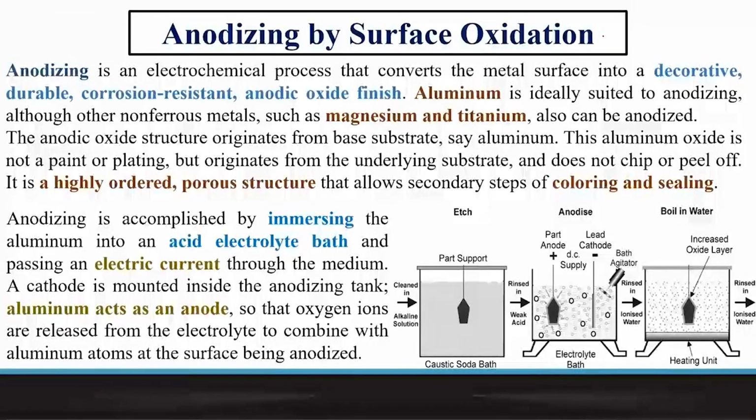Another process which also undergoes chemical reaction: in the case of phosphating, we used a phosphate containing aqueous bath, which reacts with the metal surface and forms certain oxides, phosphates and mixed compounds. And that can give the protection. That can also be used as a primer coating for further addition of paints on it.